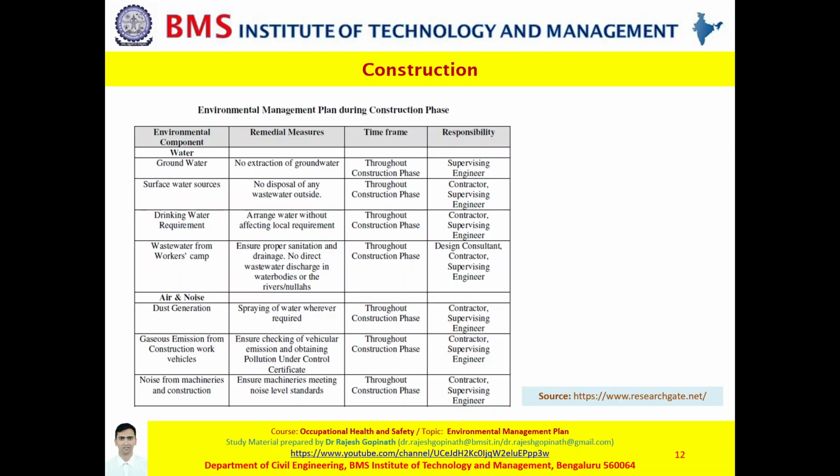So in an environmental management plan, we need to foremost identify which are the environmental parameters which could be impacted. Let us say, for example, groundwater level, or the quality of water in the lake or the river near you, or probably the topsoil, the fertility aspect, or probably the health of the worker during the construction phase, or probably the amount of pollution via noise or air.